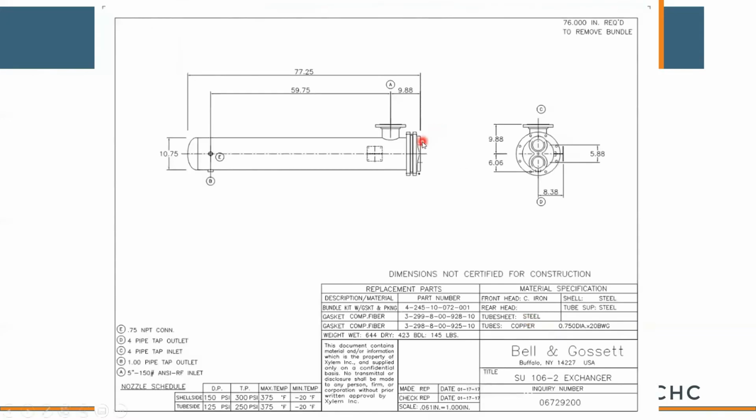The other thing to keep in mind, we try to limit our tube length or heat exchanger length to 8 foot or less, simply because we're asking for another 8 foot in front of this heat exchanger in order to service it. So if you're in a tight mechanical room, you may want to watch your overall length.